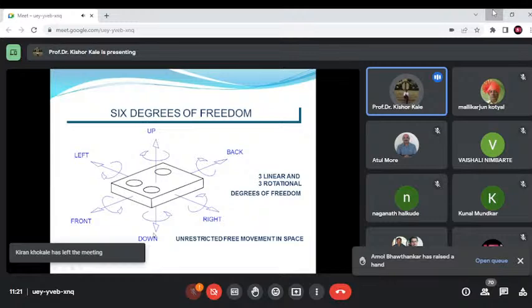Now here, the first datum is established by 3 points. So you have to define 3 different points to define a plane. So you want the surface, so you have to mark 3 different points. That means 3 reference points, when I am talking about a plane being defined. So this is very important. When a single point is there, it only indicates a single point. When we define 2 points, it actually defines a line. But when we define 3 different points, it defines a plane.